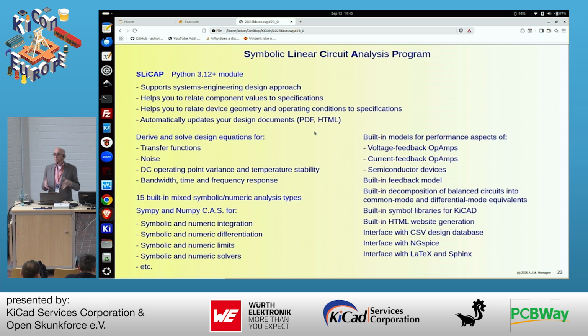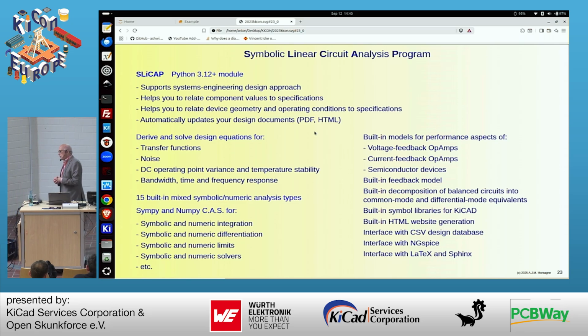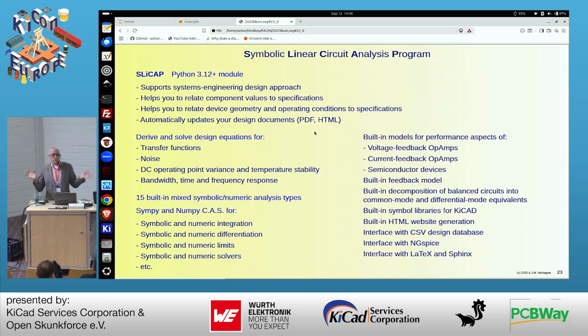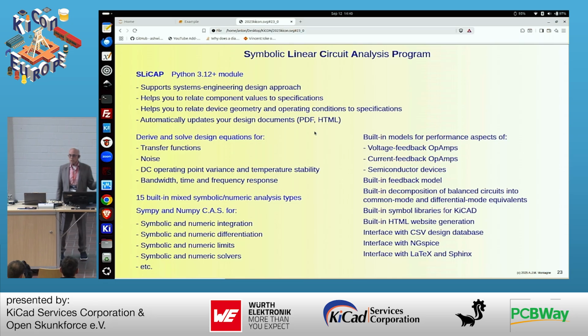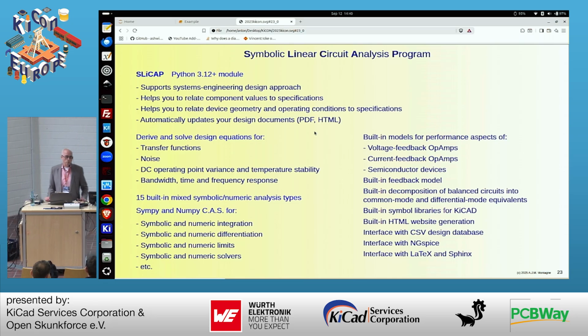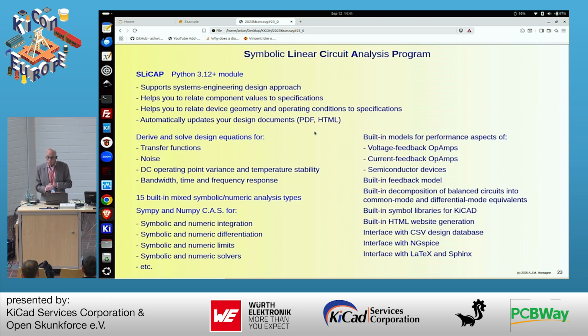We are focusing mostly on amplifiers, because the amplifier is really a basic function. So what is always relevant for an amplifier? Well, we take Shannon. Shannon is channel capacity, bits per second. So it's bandwidth, noise, and the power you can get through it. If that is lacking in the specs, you cannot make an amplifier because you don't know what you are doing. So we need to have models for small signal. Small signal analysis is unfortunately called AC analysis in SPICE, because it also holds for DC. So small signal analysis, and for unpredictable errors.